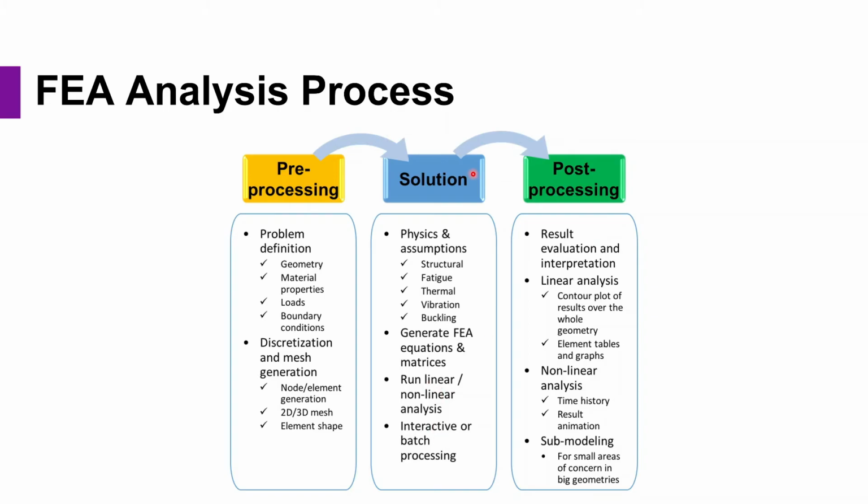Once I define everything in the solution stage, I will ask the software to go and solve the model, and every single software might use a different kind of solver. For instance, some software like ANSYS have their own solver, which is perfect, which is amazing. That's why the industry uses that. With some of the other software, such as Siemens NX, you have the option to work not only with, for instance, NX Nastran, which is the Siemens one based on Nastran, but you will also be able to use other solvers, such as the ANSYS solver, the Abaqus solver, and so on. So you will have an option to work with the other solvers as well.